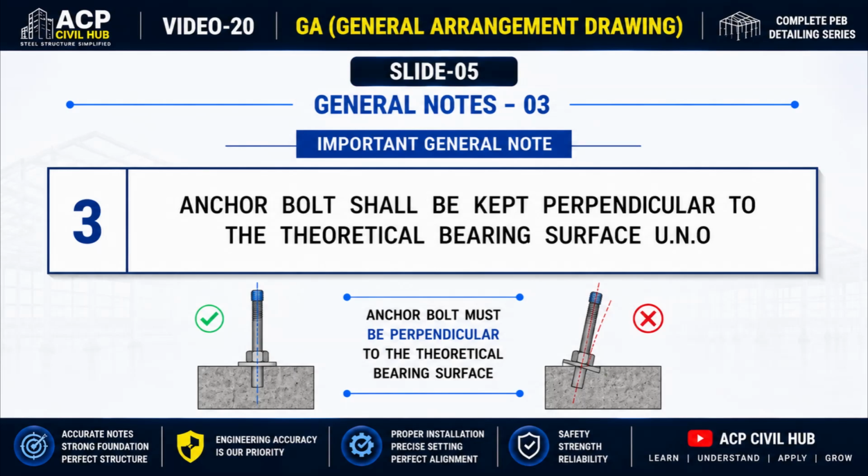The base plate holes may not align correctly. Tightening the nuts becomes difficult, additional site corrections may be required, and the connection quality can be affected. Therefore, before installing the steel column, always verify that every anchor bolt is perfectly perpendicular to the bearing surface. A small alignment error at the foundation stage can create major installation problems later.